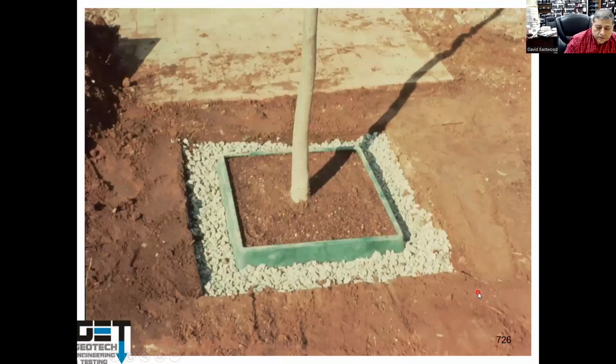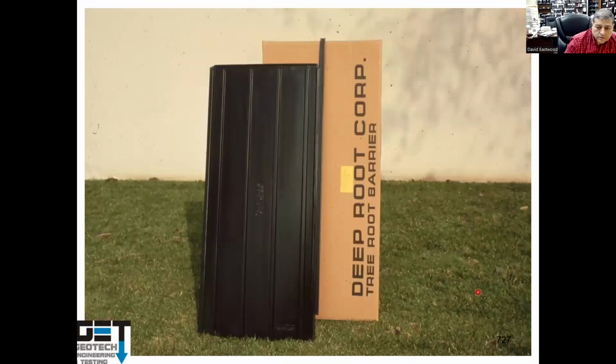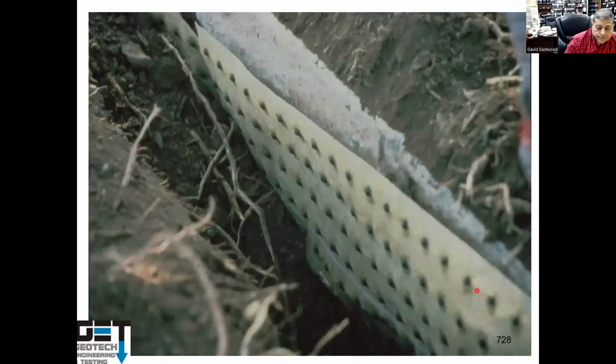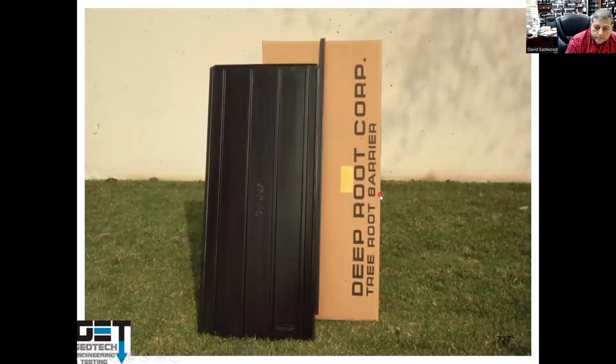Plant stuff in the root barrier. Here are the root barrier systems. Put herbicide root barriers next to the trees. The root system hits the herbicides and gets stunned so they cannot penetrate. They last 10 years. After that, they don't work. So root barriers are better, just a regular root barrier like that. This is a 15 mil fabric that you put in there.